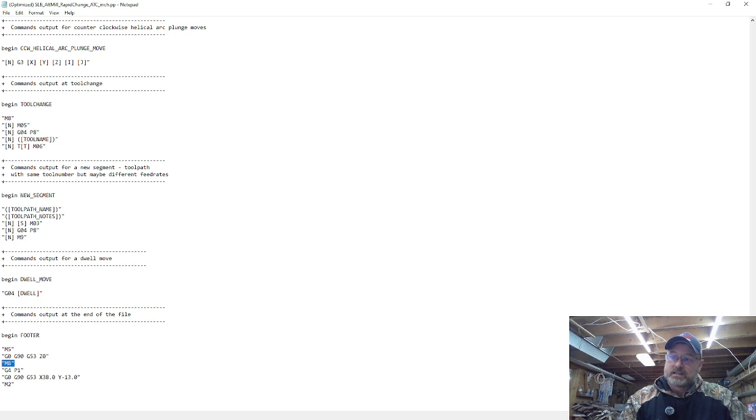And then I added in this M8 command, and that M8 command will open up the dust cover, raise the dust boot before it moves anywhere other than Z. So it'll Z up, it'll open up the dust cover, raise the dust boot, and then here I got another dwell command for pause for 1 second. And then I put in this custom park location.